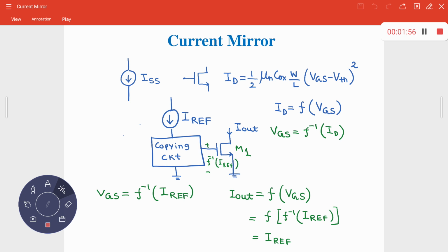Now, the design of this current source is really very difficult. Let me consider one ideal current source. If I have an ideal current source, then this current value, if I call it I of t, should be constant like this, ISS. But whenever you design such a current source, the design should be insensitive to any kind of external disturbances. What can be the external disturbances?